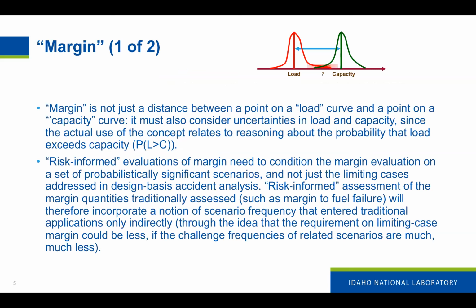The idea that we need probabilistic margin for is that if there's variability in how high it gets, and variability in the actual failure point, and there's some chance that the actual parameter will exceed the failure point, then that's an issue.